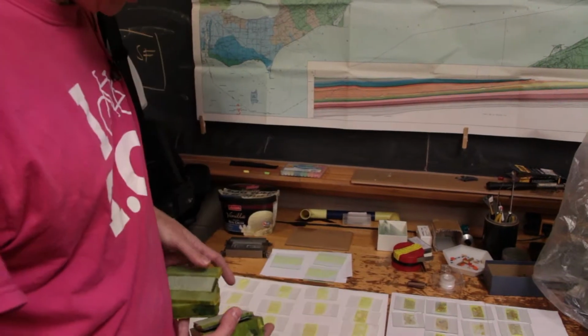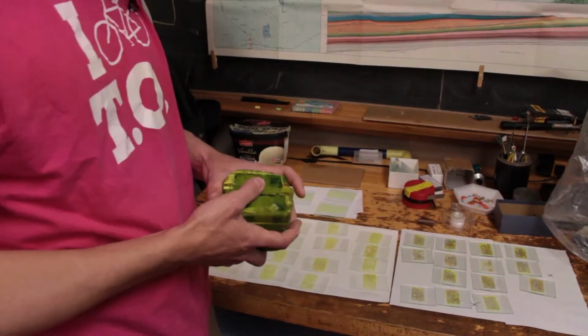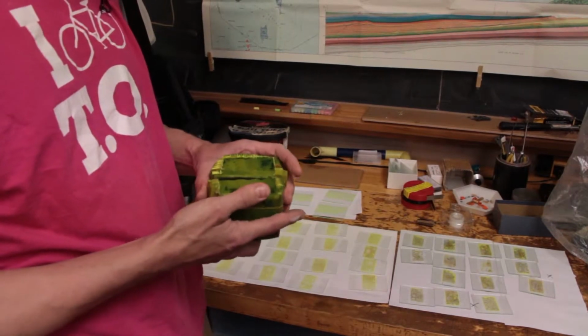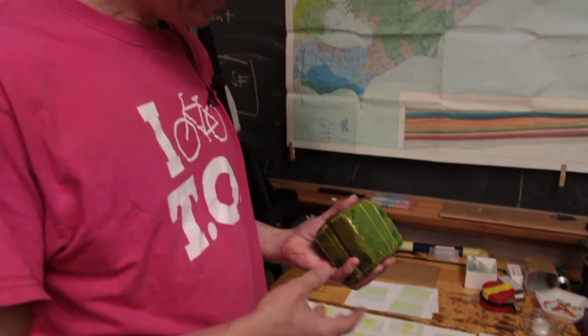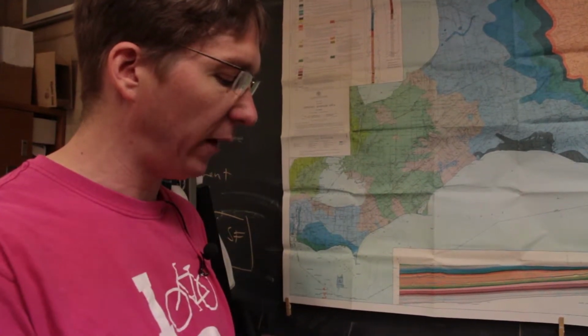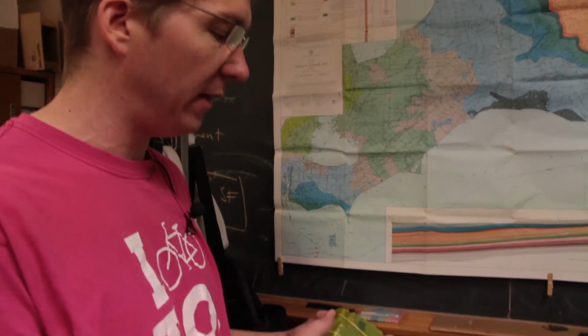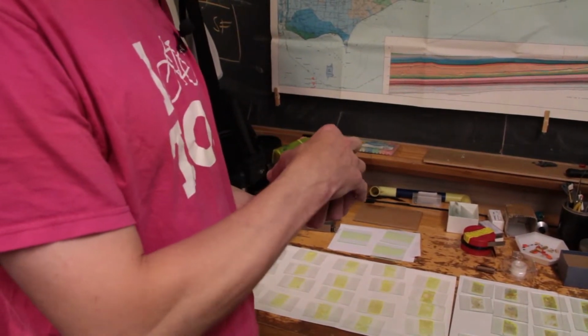We put a lot of fluorescent resins into materials so that we can study the cracks and porosity. Like this here was an 80 millimeter cube, and this is part of Professor Paul Young and Dr. Farzin Nasseri's work over in the Rock Fracture Dynamics lab. They've got these cubes that they put under different pressures and then can introduce different stresses in different directions and then study how things fracture. And they're really interested in how these cracks propagate.